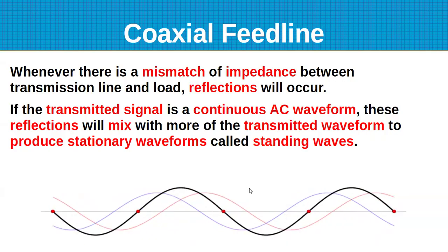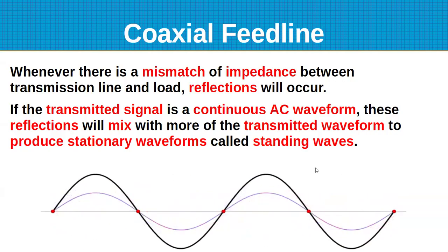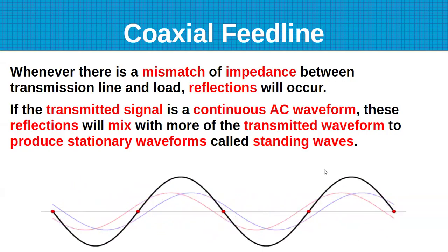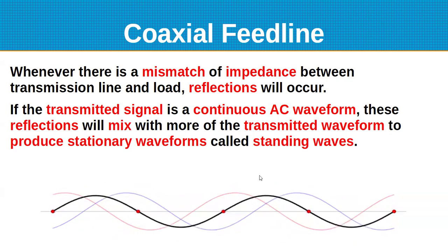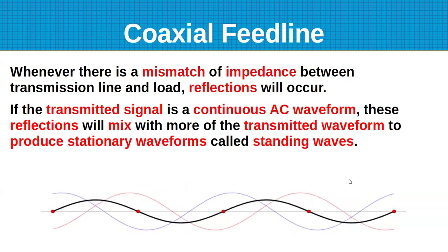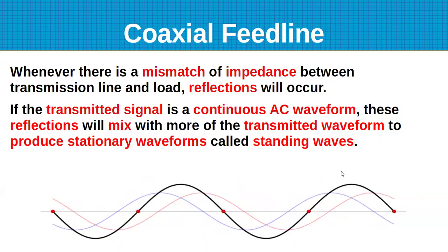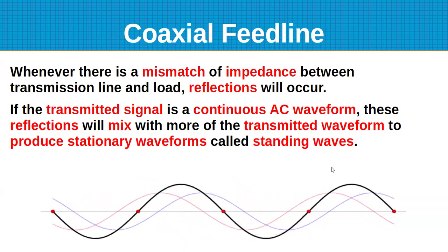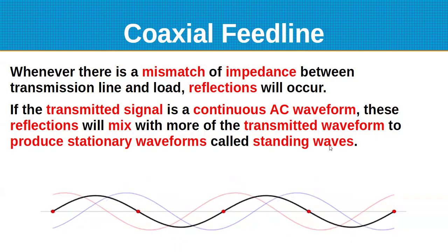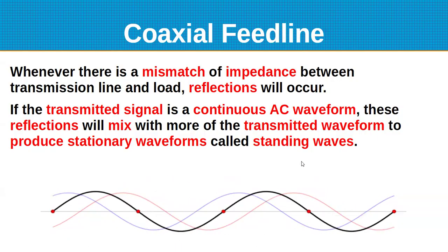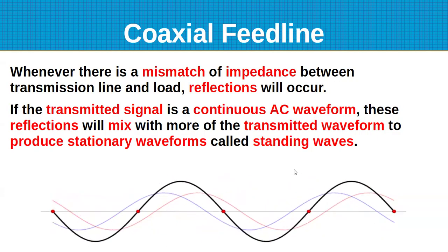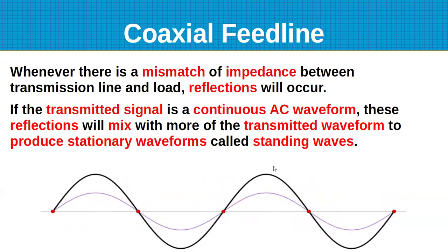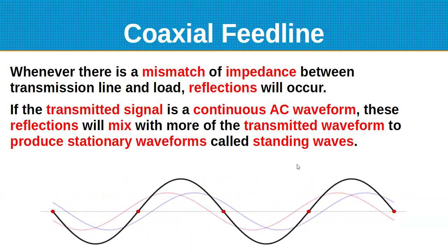So you want to try to eliminate it, and we'll get to things like common mode chokes later. The whole purpose is to provide an impedance on the outside of the coax to block that current. Right. So you can put a ferrite on there and help.